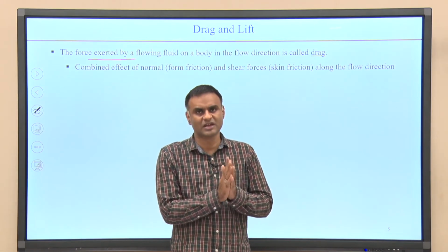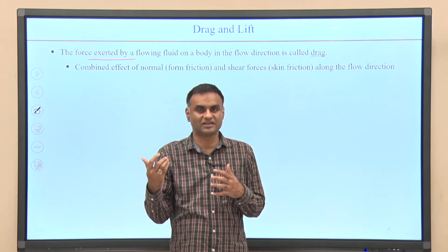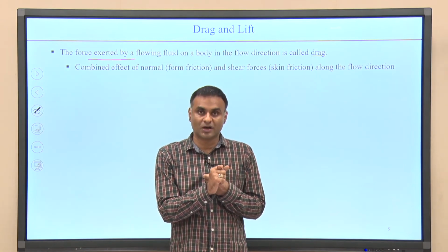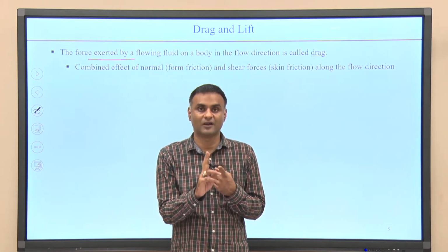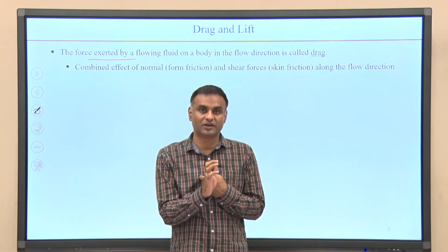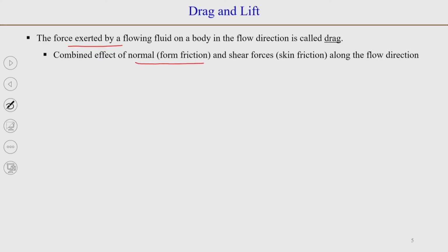In most other cases, especially at high Reynolds number flow, the viscous normal stresses are generally negligible. So, you will have pressure forces contributing to the drag, and viscous forces contributing to the drag. Now, the effect of normal forces or pressure forces, we can say here, comes under form friction.